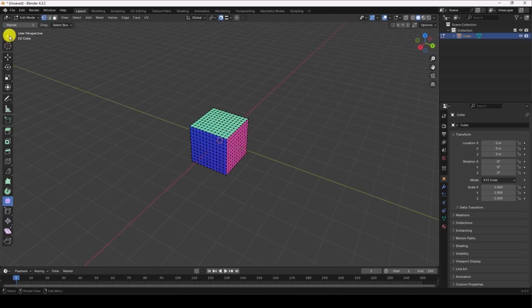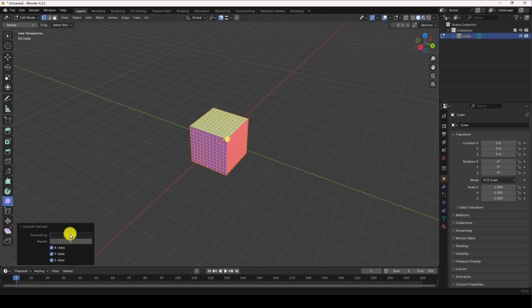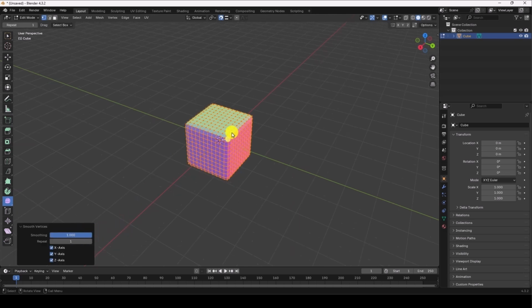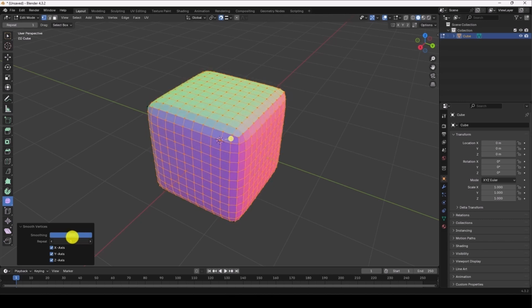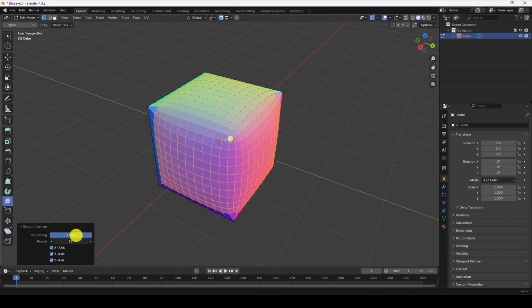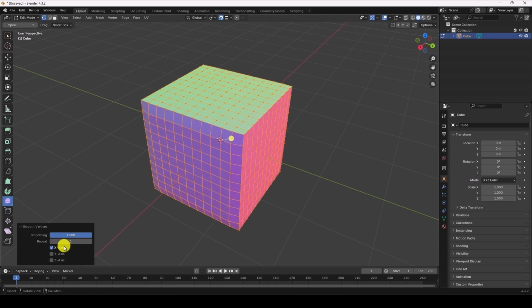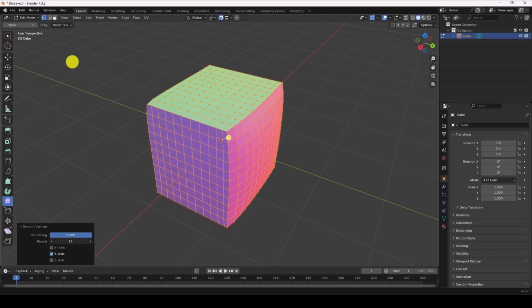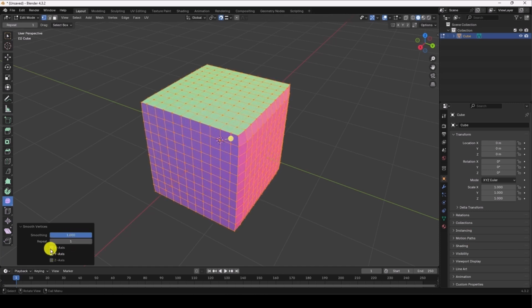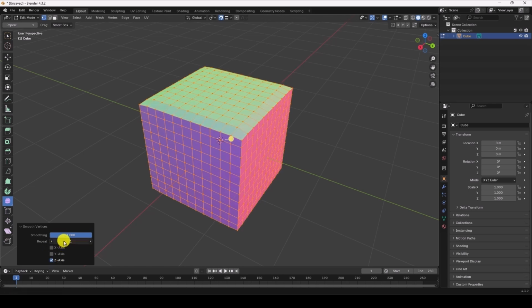After subdividing, select the item, apply the Smooth tool, and then adjust the smoothness. You can move the yellow handle directly from Object or increase/decrease the smoothing value using the small menu located at the bottom of the screen. You can also control how many times the smoothing should be repeated. Additionally, you can specify whether the smoothing should only apply along the y-axis, z-axis, or x-axis, depending on your preference. The effect will vary based on the shape of the object you're working with.